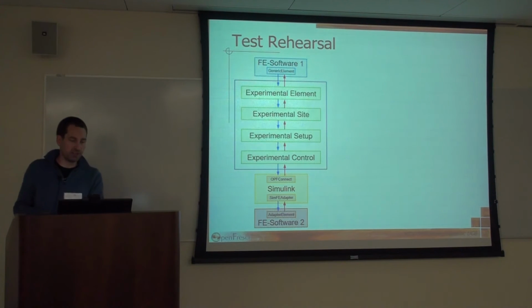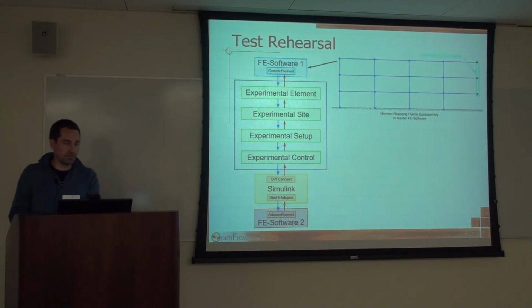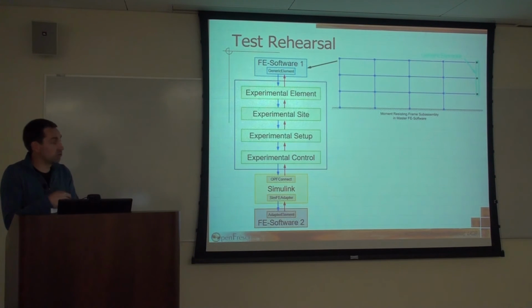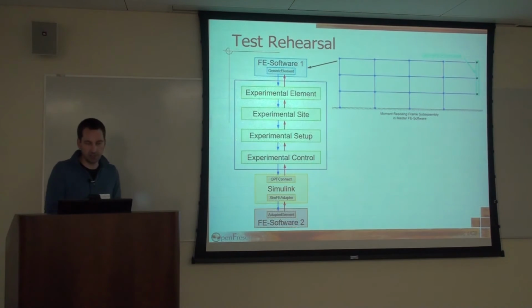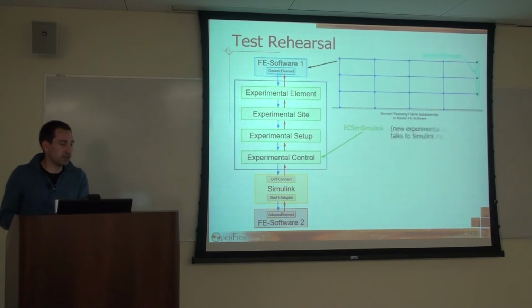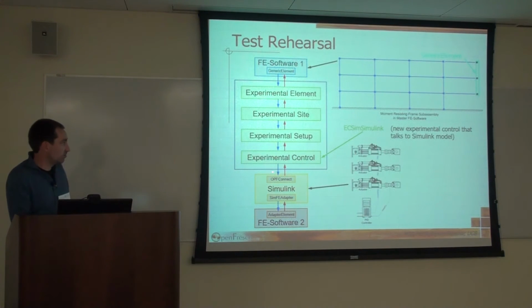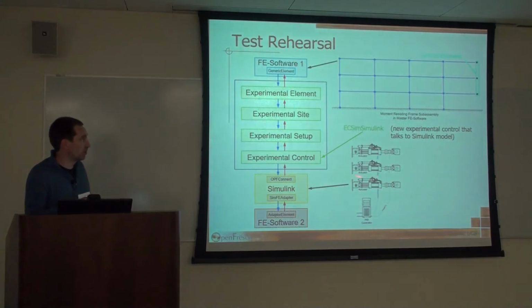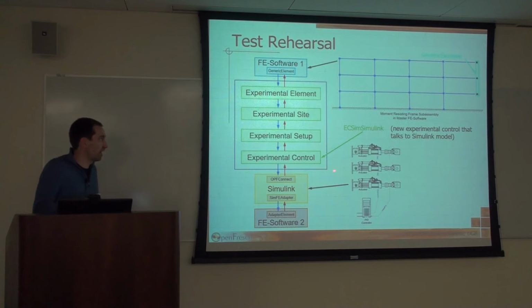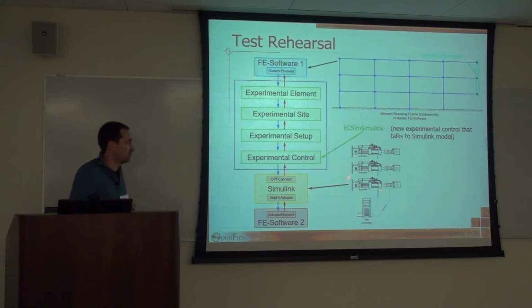The test rehearsal we have already heard a little bit about. Another very nice thing to do with OpenFresco is to do an actual dry run before you go into the lab and do your real test. When you do a dry run, it's often very important that you simulate the dynamics of your controller, the dynamics of your actuators, maybe even the hydraulic power supply, everything. MDS has developed very nice Simulink models to capture all these dynamic effects coming from the control, from the actuators, and so on. These Simulink models sit here.